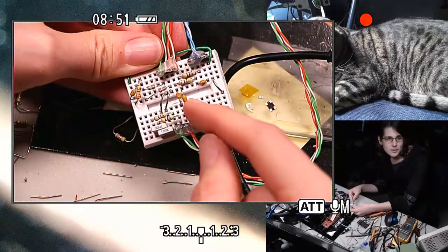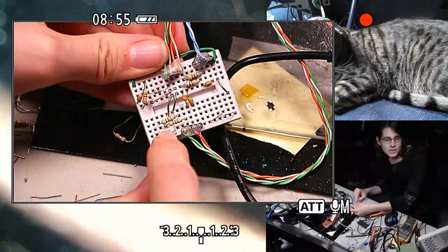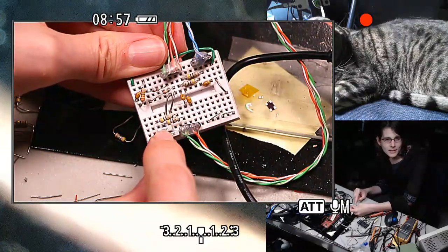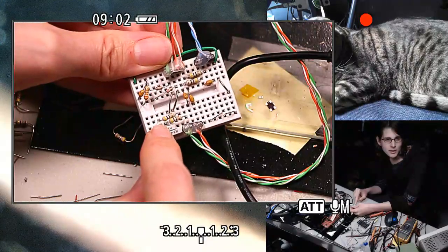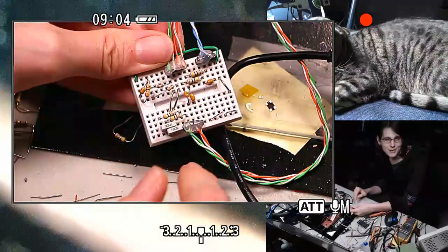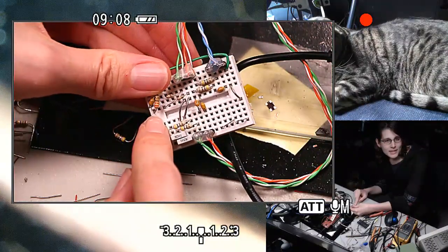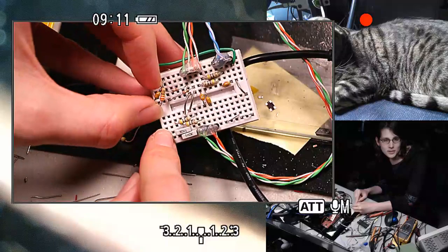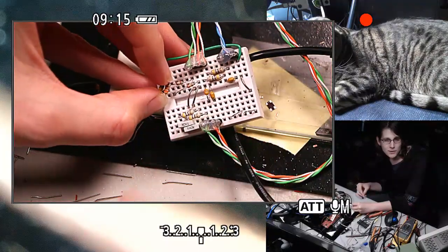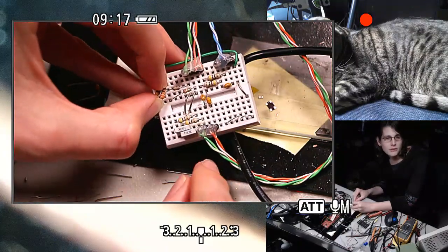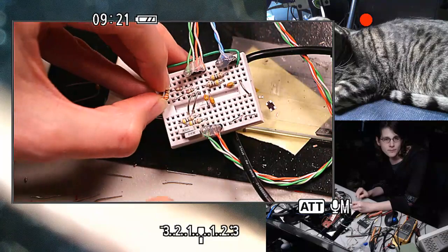So, you know, these capacitors up here are like 0.22 microfarads. Out of the capacitors I had handy, having a capacitance of 1 nanofarad on the other side seemed to work better with the different impedance of that driver, I guess. And then over here is an experiment in biasing. I was connecting a power supply across this resistor and capacitor and using that to try to get a stable 1.5 volts or so, and I was adjusting it, trying to see if I could set the bias point to different levels and see if I could get packets through.